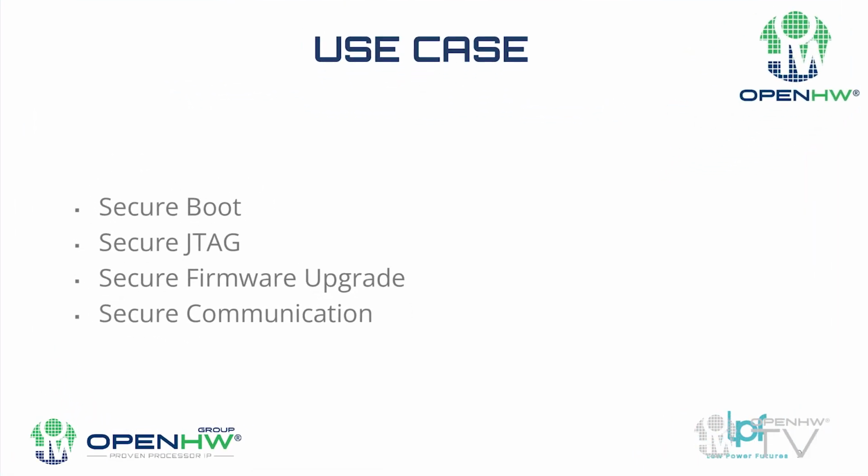The main use cases of the trusted MCU are secure boot, to make sure that the firmware or the bitstream loaded onto the device is trusted and coming from a safe source. Secure JTAG, especially for debugging during the early stages of the life cycle. Secure firmware upgrade when the device is already deployed in the field, and also secure wired and wireless communication.